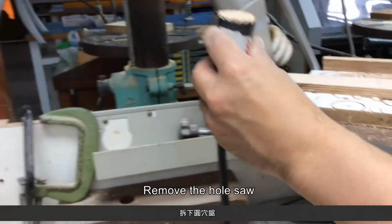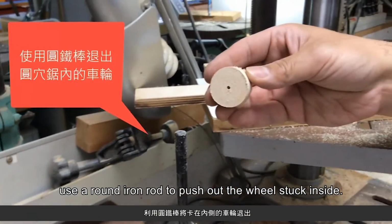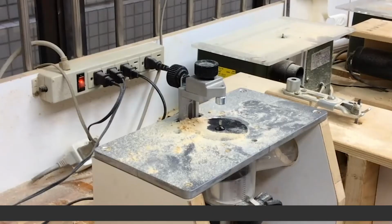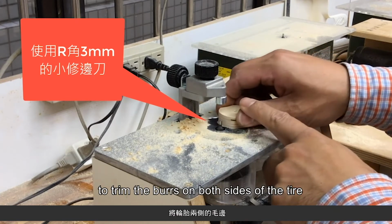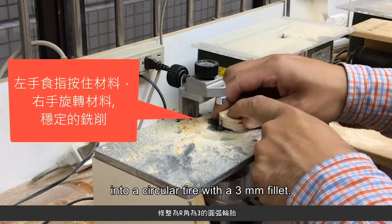Remove the hole saw. Use a round iron rod to push out the wheel stuck inside. Next, we use the router to trim the burrs on both sides of the tire into a circular tire with a 3mm fillet.